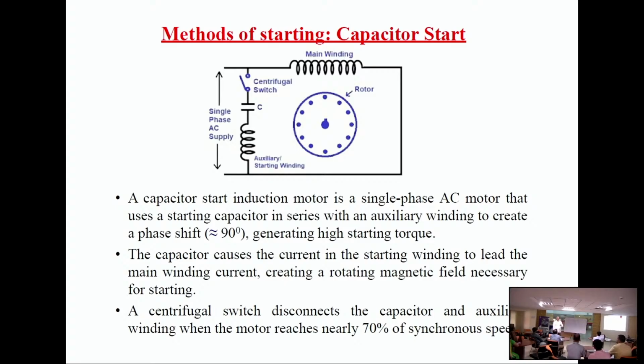If it starts rotating, then you can remove it. The centrifugal switch acts at a speed that you can ensure during design.